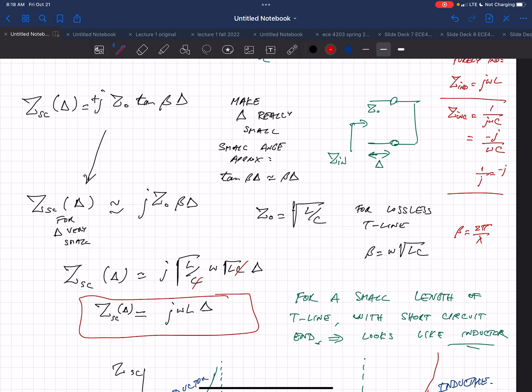Yeah. So when you're looking at a transmission line, let's think of three different cases. You have a completely matched transmission line, meaning the characteristic impedance of the line is the same as the load. That way you don't get any standing waves, you just get signals going through. As soon as you get either a short circuit or an open circuit on the end, or anything unmatched, you actually get a standing wave in the transmission line if you're giving it a purely single frequency.